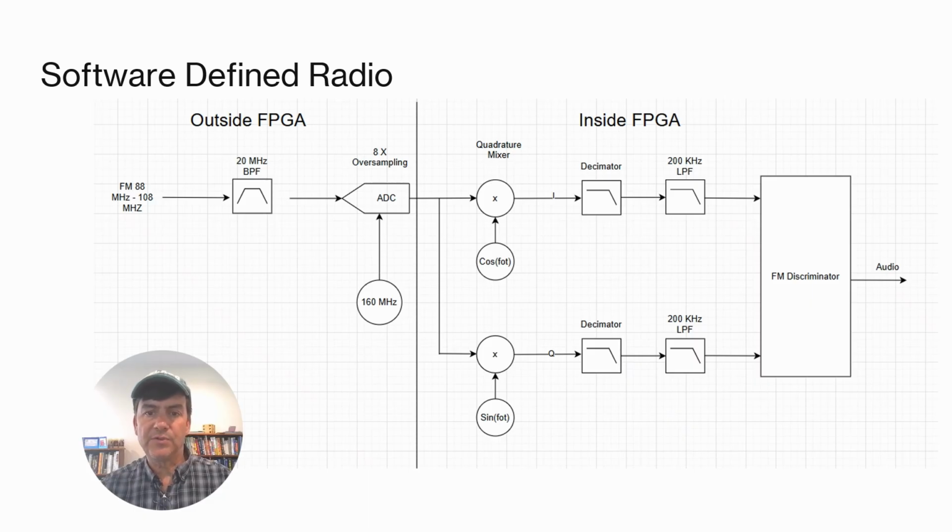At this point, a natural question arises when viewing the SDR diagram. Why do we need both a low-pass filter and a decimation filter? The short answer is that using a single filter is impractical, and in many cases using more than two filters is actually beneficial. To understand why, let's turn our attention to FIR filters.